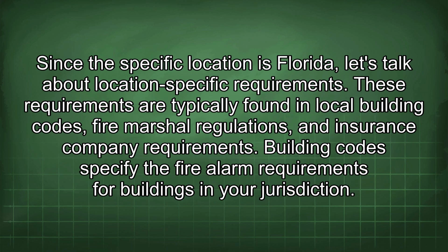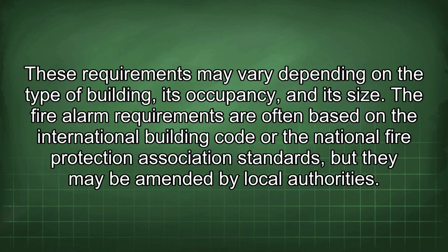Since this specific location is Florida, let's talk about location-specific requirements. These requirements are typically found in local building codes, fire marshal regulations, and insurance company requirements. Building codes specify the fire alarm requirements for buildings in your jurisdiction. These requirements may vary depending on the type of building, its occupancy, and its size. The fire alarm requirements are often based on the International Building Code or the National Fire Protection Association standards, but they may be amended by local authorities.